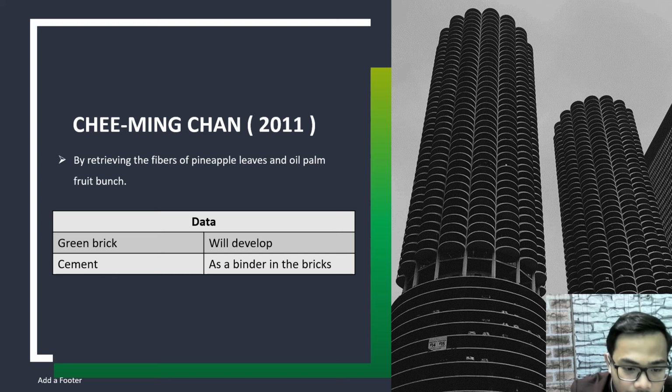In this way, green brick materials are developed, which leads to the reuse of natural waste, avoiding hazardous waste dumps and open burning. Cement is also added as a brick binder, and both unburnt and fired bricks are prepared. Cement was found to dominate the compressive strength of brick. Unburnt brick crumbles when immersed in water, while baked brick shows cement-dependent properties in the water absorption and density change.